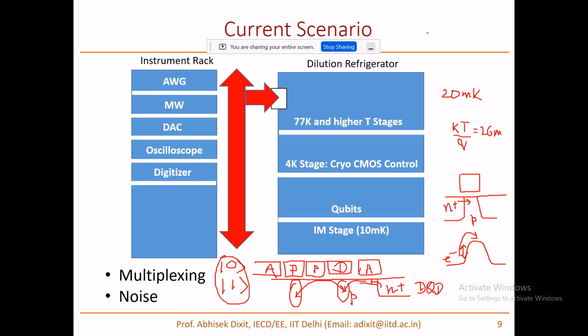So while your logic bit, you can say this is either 0 or 1. This is what we have understood in the second year BTech courses, that a logic bit can either be in state 0 or state 1, depending upon what your assertion level is. Could be positive logic, negative logic, but there is a 0 and there is a 1. No third state is allowed, right? A logic bit cannot be in any state other than a 0 or 1. If it gets stuck in some metastable state, the circuit will do something to bring it to one of these stable states. So this is basically a bistable multivibrator. So two stable states, 0 and 1.